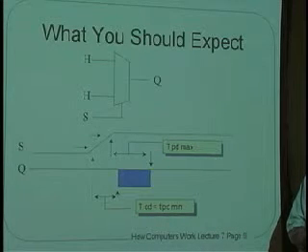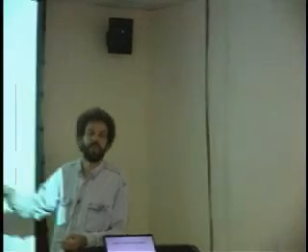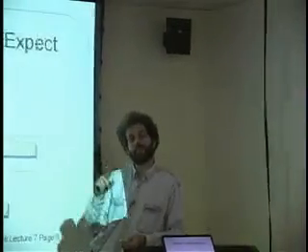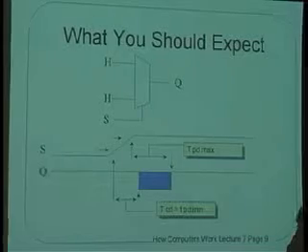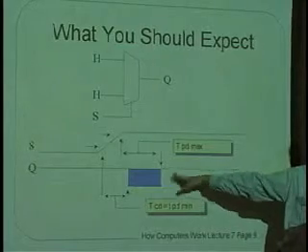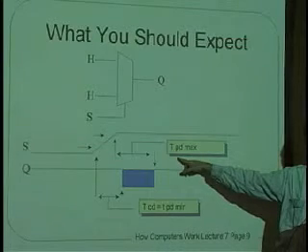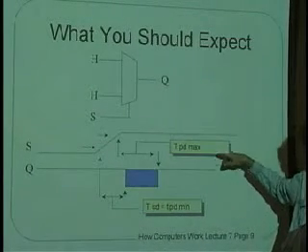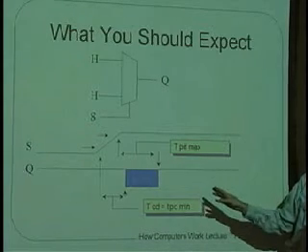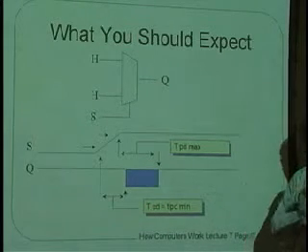But it's actually okay. Inside of your computer, at any given time, a lot of the wires are in these intermediate states. And what's great about it is that the succeeding circuits are not looking at the wire when it's doing that. If you remember our finite state machine timing diagram, that D flip-flop, the D register, did not sample its input until after all of this blue time was done. It waited until the TPD max had finished of one circuit, and then the next one, and then the T setup was done, and then we triggered it. So it's okay for these glitches to go on, as long as we're not watching the signal when it's going on.